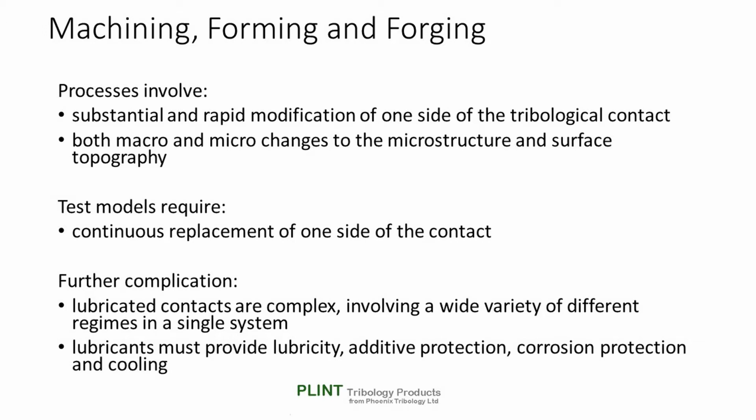A further complication is that the majority of lubricated contacts are complex, involving a wide variety of different regimes, boundary, mixed, and hydrodynamic, in a single system. The lubricants involved must provide lubricity, additive protection, corrosion protection, and cooling. In both dry and lubricated systems, tooling and coatings must be chosen to be resistant to material transfer, in other words, pickup and galling, thermal and mechanical shock, wear and surface fatigue.